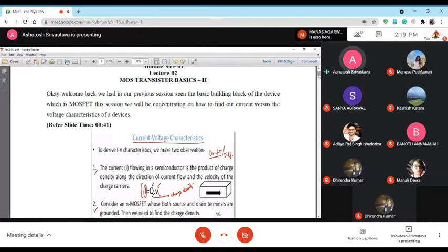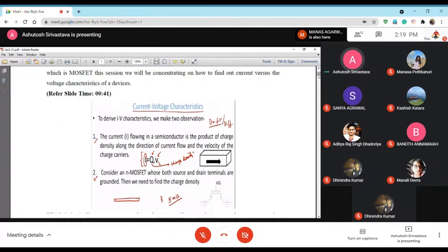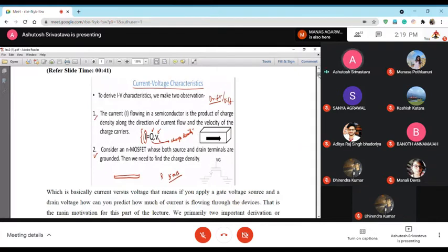And essentially what happens is you are having a planar thin layer of inversion happening just beneath the silicon dioxide, which is the insulator surface, and there is an effective electric field.